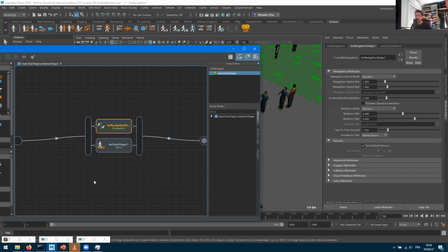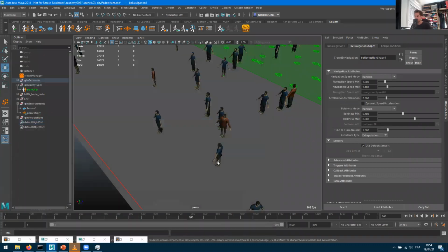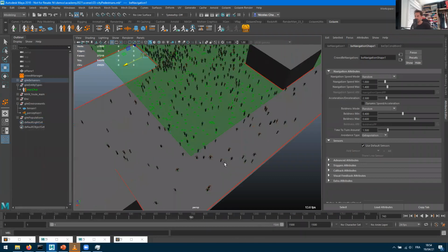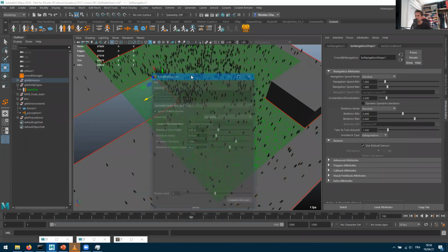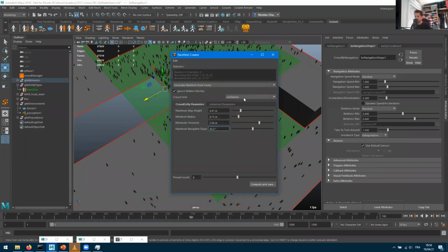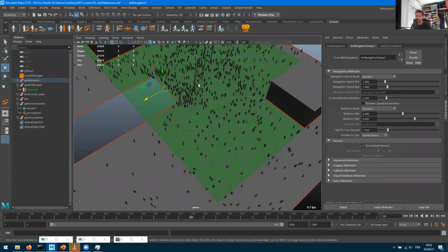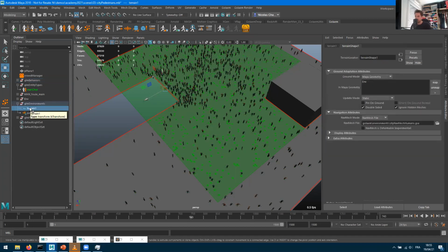If you get any error regarding targets not being found or whatsoever, it means that your terrain is not correct, that you haven't changed the unit properly, and even if it looks like the red borders are there, your environment is not set up properly. It means that you haven't set your crowd unit to centimeters, and when you don't do that, the environment is not the right size, so the characters could not reach it. In the meantime, if anybody has issues with terrain not being reachable whatsoever, join to your terrain here.